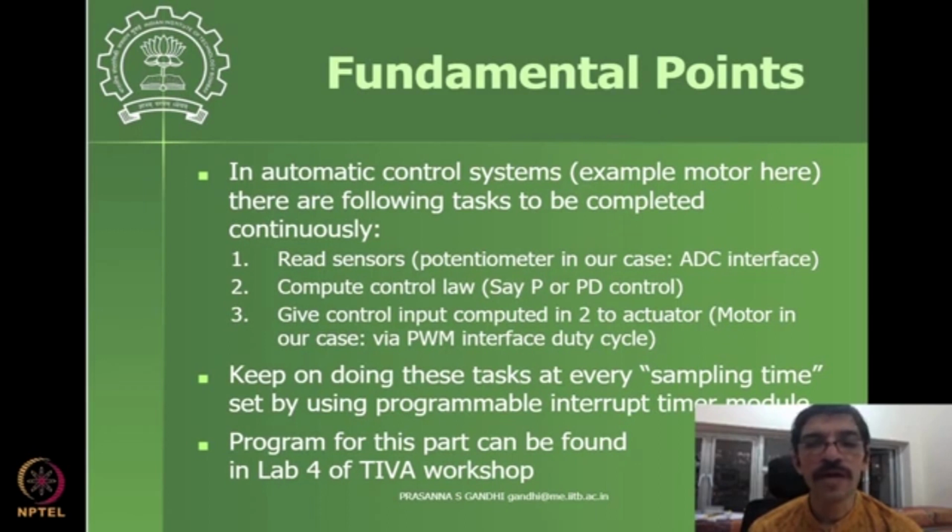Why we keep this as interrupt-based sampling time programming, we will discuss as we cover sampling and other issues in more detail. We want a fixed, known sampling time for the operation to happen periodically, and this job will be done.